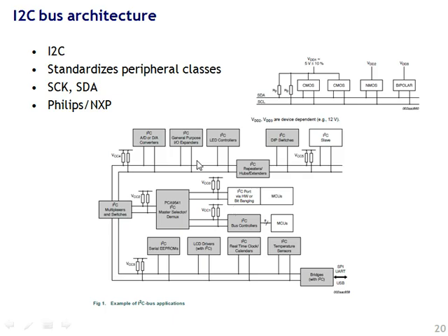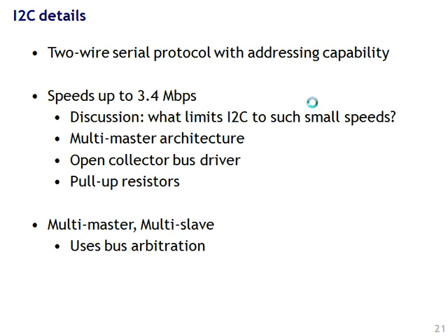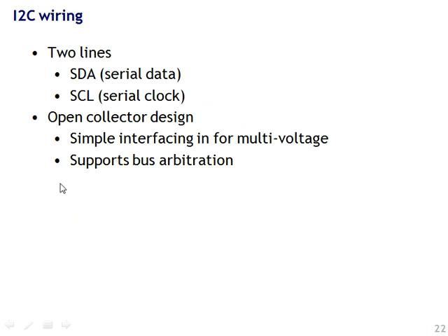I'll just tell you what some of this stuff says. I2C DIP switches. So you can control the switches with the I2C bus. Speeds, not particularly fast. 3.4 megabits per second. Very inexpensive. It has 2 lines of clock and data.